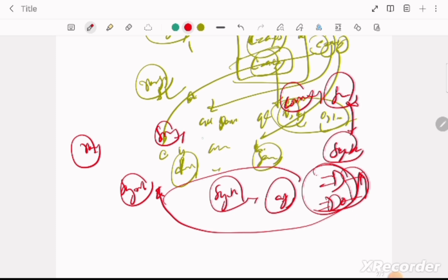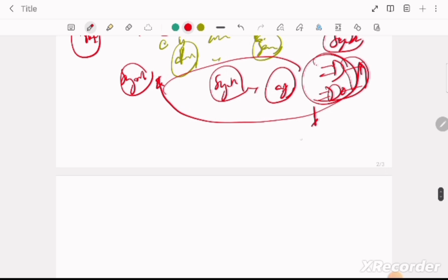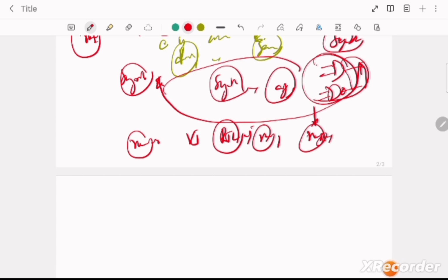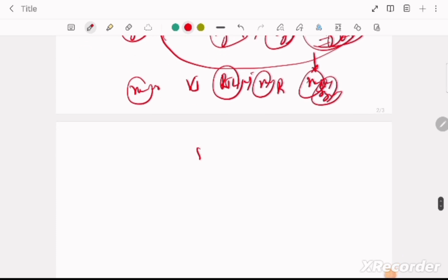At simulation we will check the code, the algorithm that we have written for solving the problem, whether that is correct. And at the time of getting the netlist, we have to verify at that time also. So with that we will require verification at 2 stages till now. After that we might require more, but till this stage. After writing some RTL code, we verify this. We will simulate the design, and we are not performing the synthesis here. We don't care how synthesis will work at the time of RTL simulation. We don't care for synthesis.